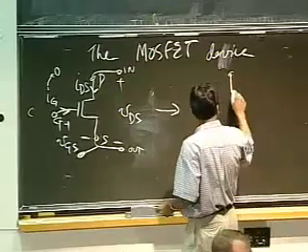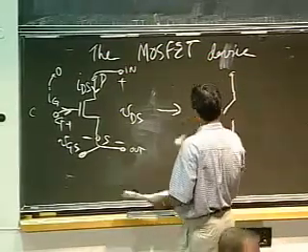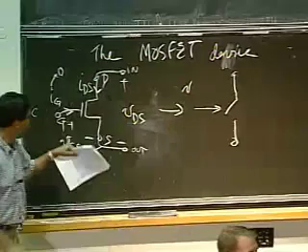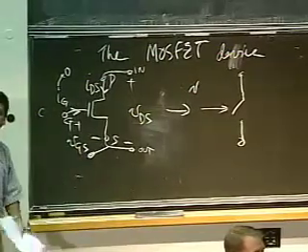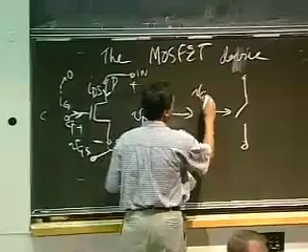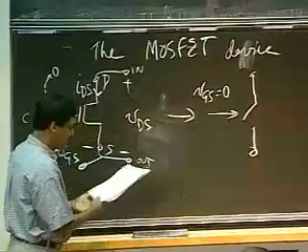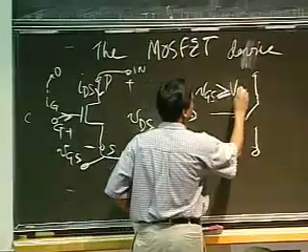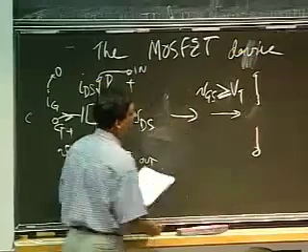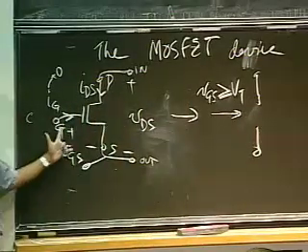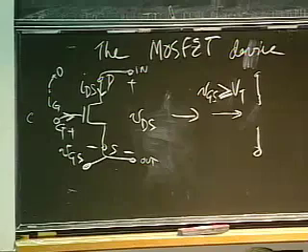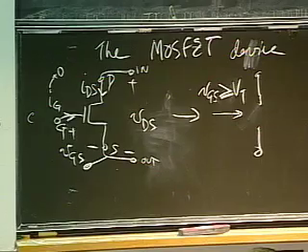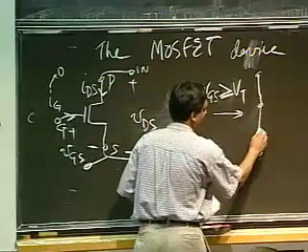And so in this particular situation, if its behavior is characterized by the voltage applied to VGS, much like the control on the switch, VGS is my control. So when VGS is 0, if VGS is greater than or equal to some threshold voltage VT, okay, so if VGS, the voltage applied here, is greater than some voltage, VT, a threshold voltage, or the pressure on the switch is greater than some threshold pressure, then this guy behaves like a short circuit.